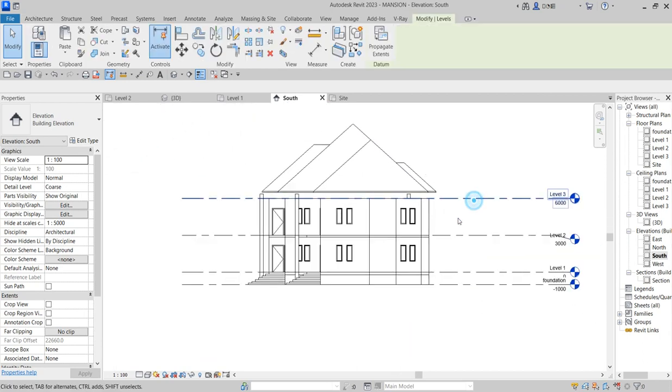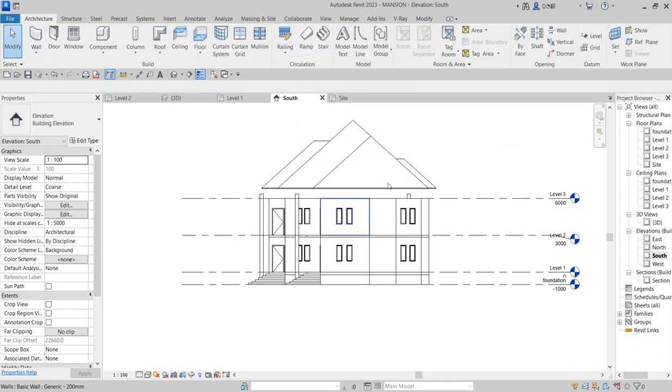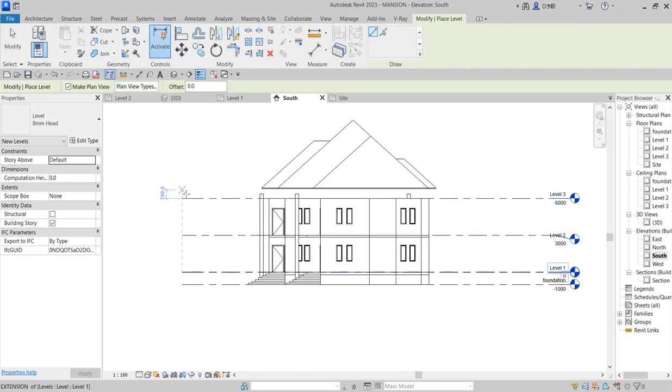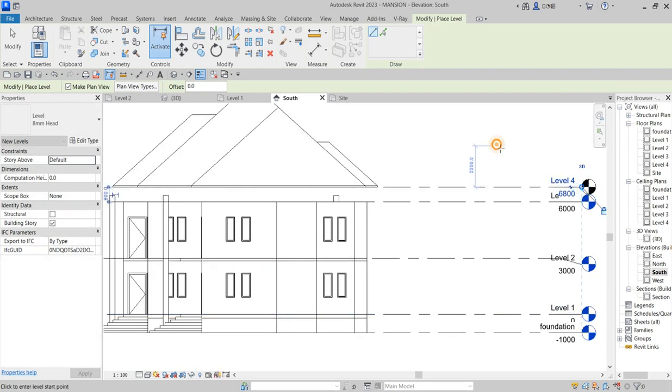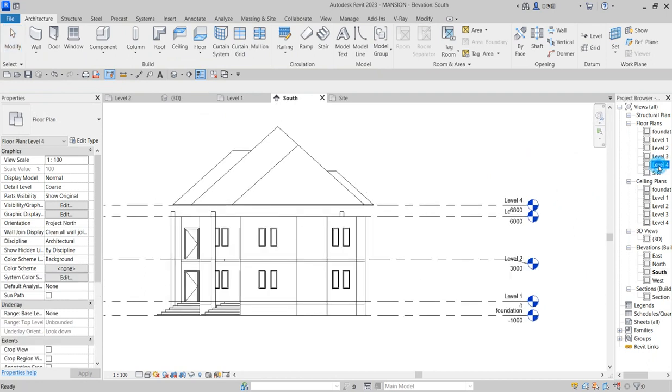Now I want to create another level. This level is going to be a minor level. I want to increase this one to, let's say, 200. Okay, let me add it to say 800. Good. So now I'm creating another level from here by clicking on this and say create another one. So at this another level, I'm creating 800. I want you to snap to that roof. Good. So I'm going to go there, go to that level 4.